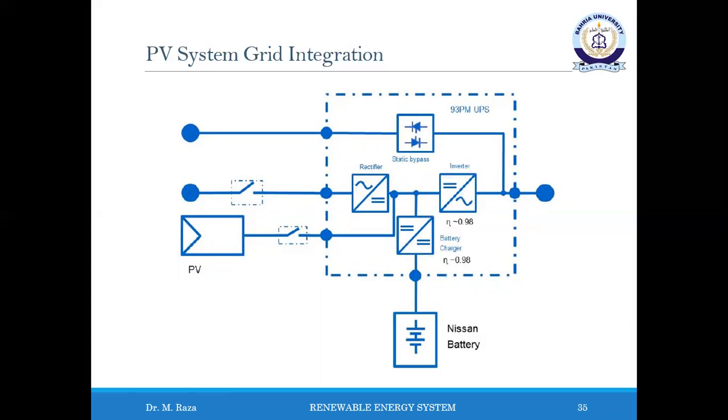However, some drawbacks are related to this solution. The DC bus voltage of the UPS is regulated and the voltage level has to be kept in a certain limit in order to perform its basic operation as a UPS device. In this topology, the PV array voltage should be specified to that same narrow voltage range.